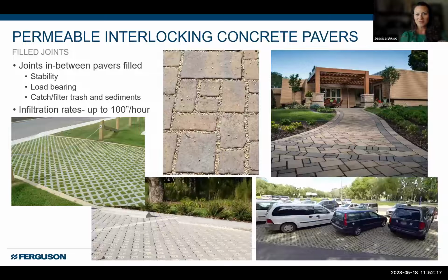So again, our filled joint pavers. The pavers are put down, and the pavers, of course, are not permeable in and of themselves, as Evan described before, but the water is going to percolate in between the pavers, through either the sand or pea gravel, whatever is the case for those pavers. You can see a couple of different examples up here, right up in the middle, and also over with this walkway.